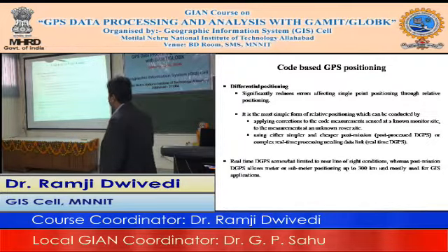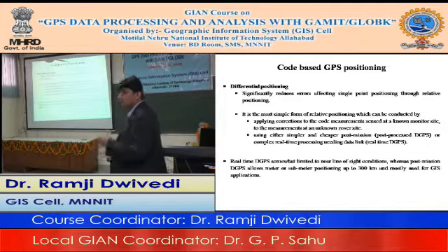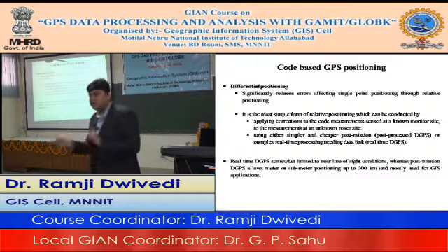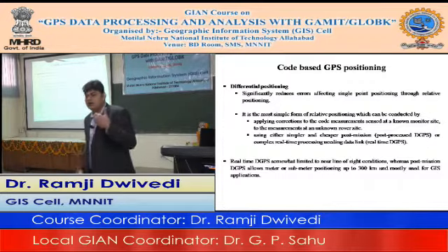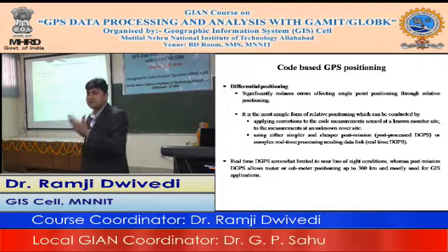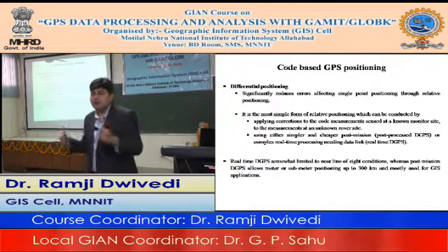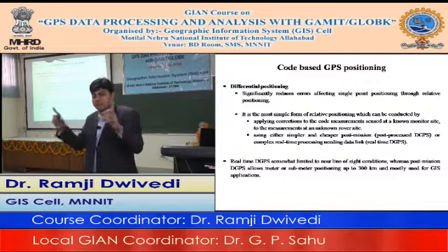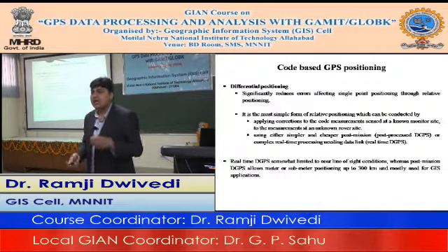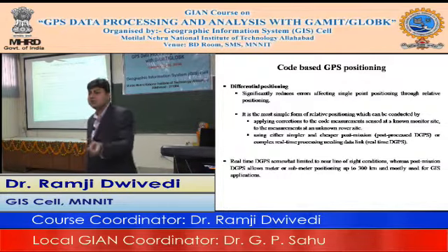So this significantly reduces, not removes, reduces errors affecting single point positioning through relative positioning mode. As I said, in literature you will see that relative and differential are used interchangeably, but in general we use the word relative for phase based, and when someone says we have done a DGPS survey, he is majorly talking about the corrections to the code pseudo ranges at the rover.